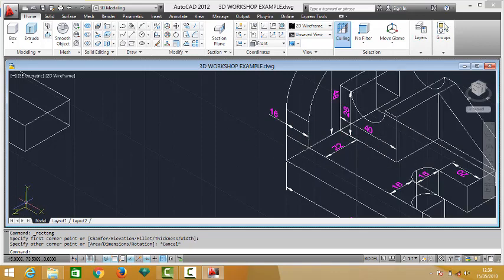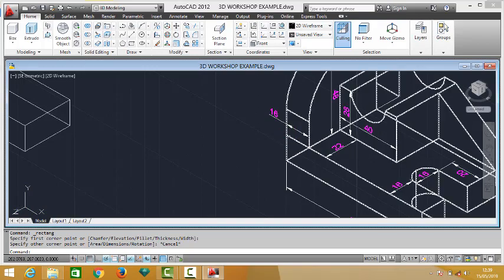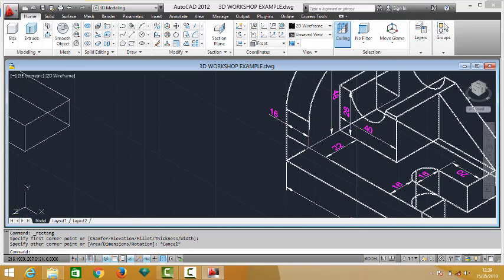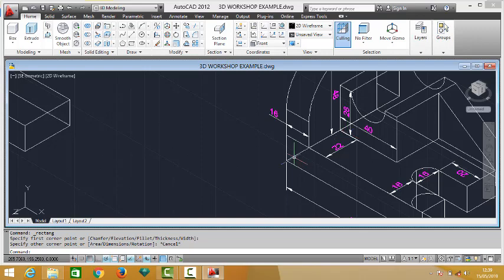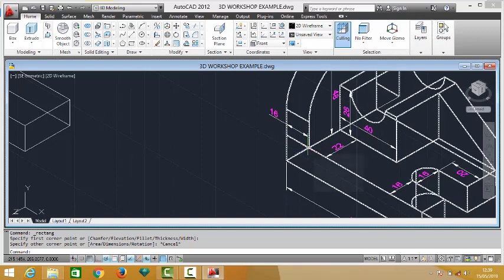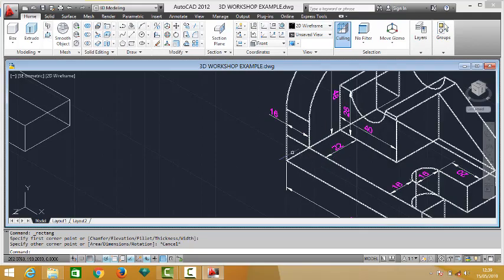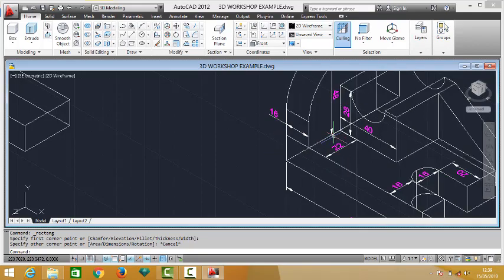Now if you look at your XYZ coordinates, if you are here and you are moving here, that means you are moving X. And then if you are here, you are moving here, that means you are moving Z. Actually, you are moving to the negative side of Z. So that means if you are here, you want to get here, you move X 16. And then you want to get here, you move Z minus 22. Meanwhile, Y will be 0 because you are neither going up nor down.